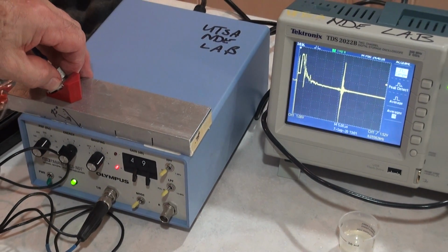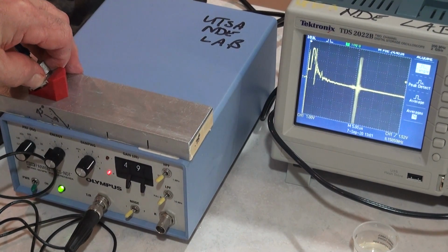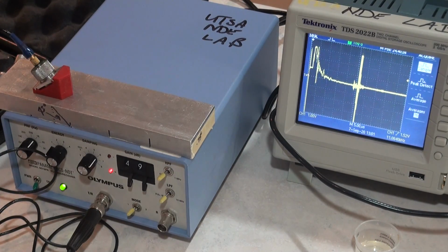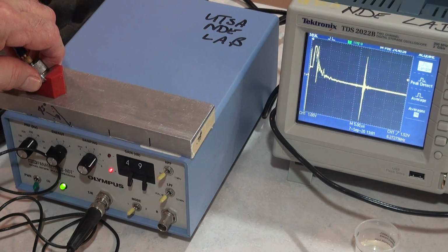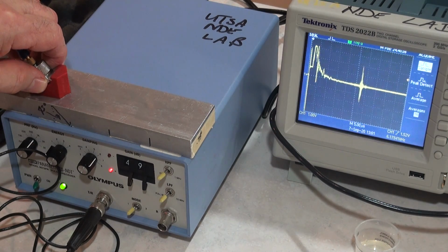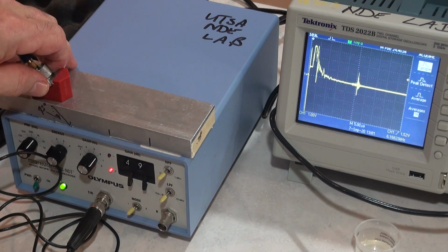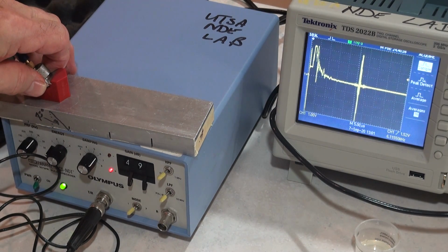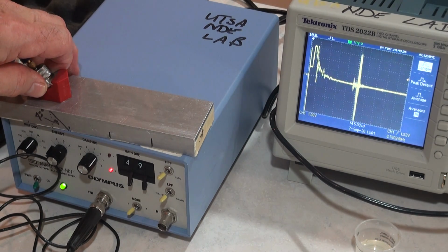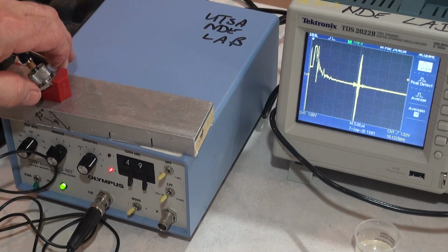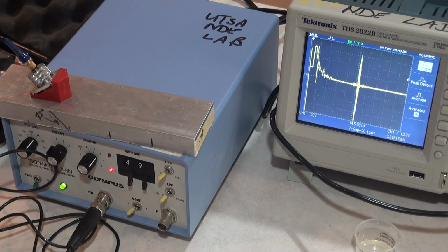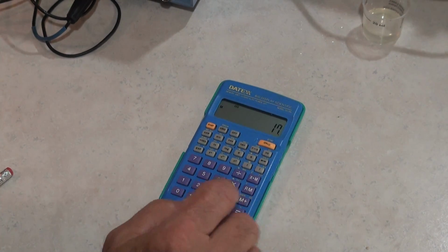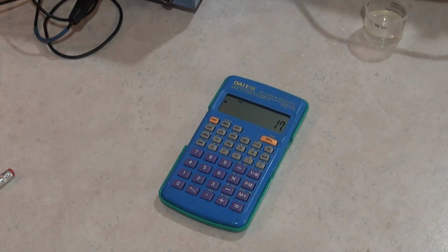All right, now the interesting thing, let's calculate the time it takes to get to that big signal. Okay, so right now that signal is about, hang on just a second, let me get it peaked up. Okay, the signal is right at 25 microseconds. Okay, so if I take 25 and subtract 8 from that, which is the time it's in the wedge, then I end up with 17 microseconds.